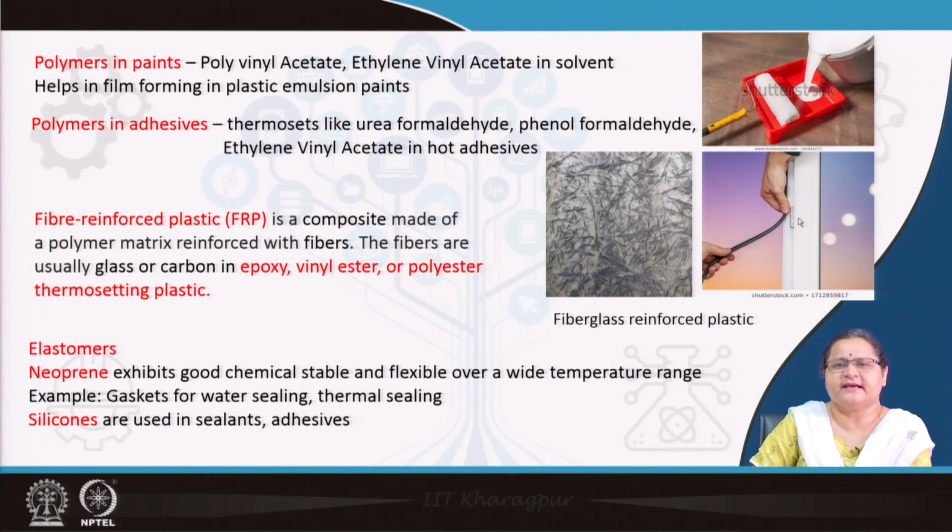So, when it is a case of insulation of, say, a double glazed window, you have to have neoprene gasket all around. You can use silicone gaskets, silicone as adhesives when you are using precast concrete slabs.